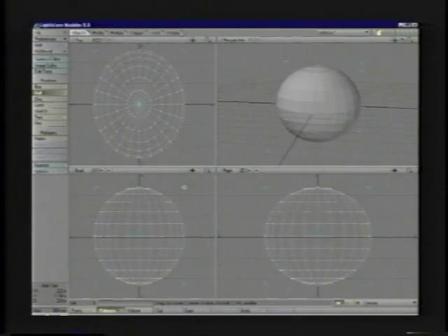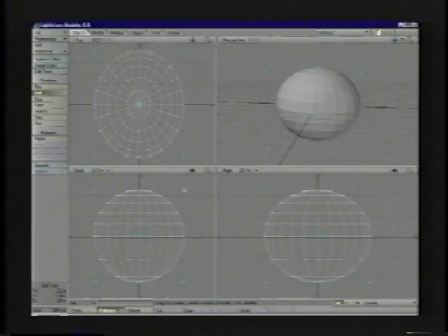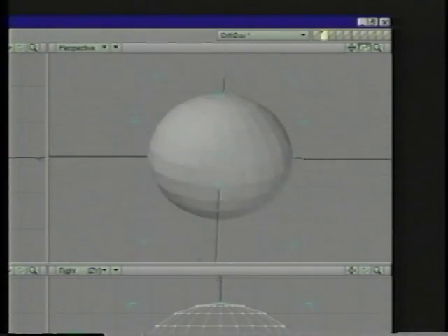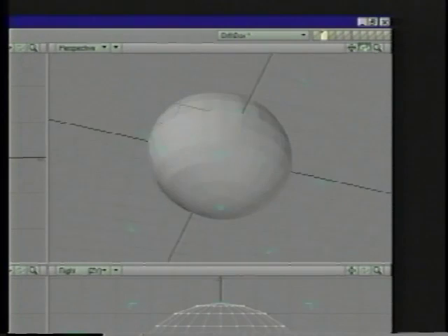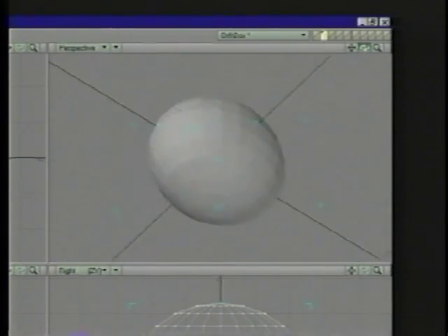But let's go ahead and create the ball by going down into the back view, left mouse button, drag it up, holding the left mouse button down, and now we can drag out the other dimension of our ball, into sort of the Y dimension, the third dimension. Okay, so over here in the perspective view, if we swing it around, you'll notice that we have a nice ball object in there.